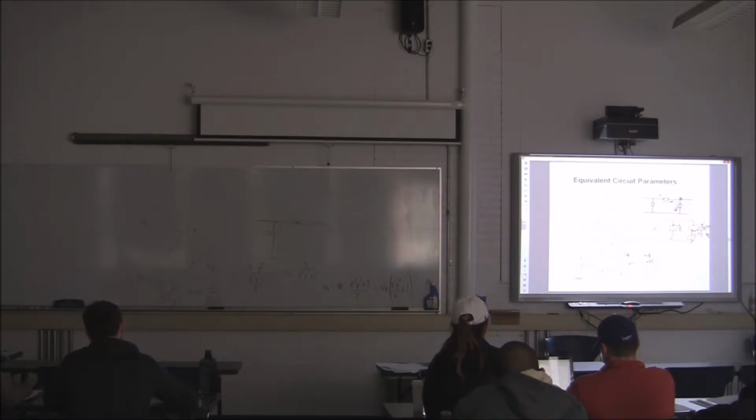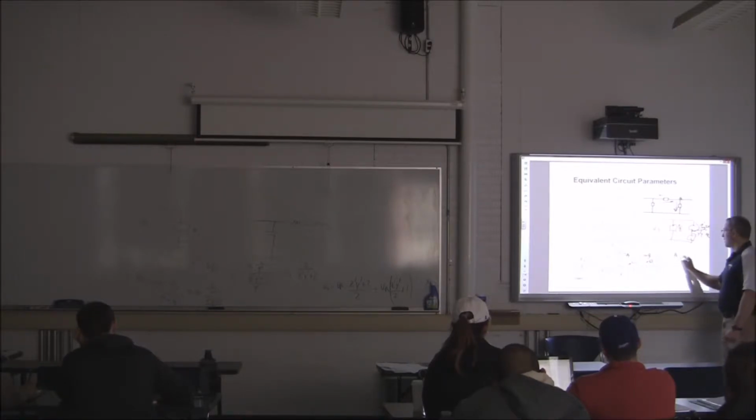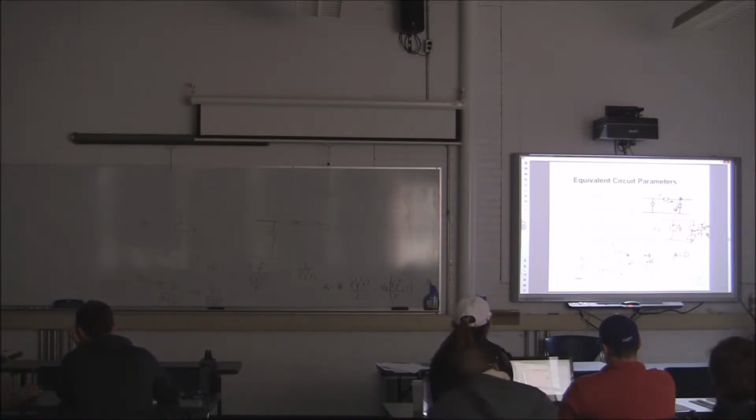So when I use the pi equivalent model of a transmission line, I'm going to substitute in Z prime and Y prime, and then rearrange my circuit or my ABCD so I have these terms. You will note A and D equal the same. They're the exact same. Okay?